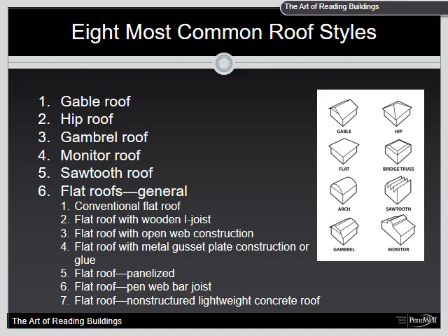The older the building, the greater the possibility of multiple layers of roofing material that the roof was likely not designed to hold. In some cases, roof ventilation operations might be able to be conducted within close proximity to the fire on a conventional construction.